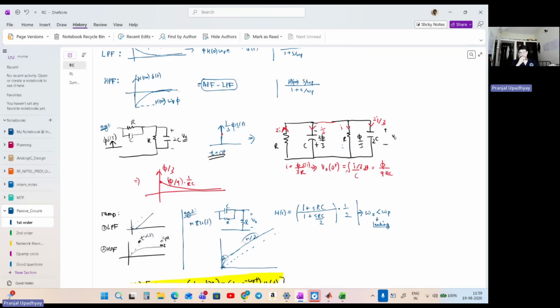Now, here, just by the look of it, typically they will mention also, but this is basically a voltage impulse. Now, let us try to discuss the behavior of the circuit. So, at infinite frequency, what will happen is that this capacitor and this capacitor will short, and basically voltage division will happen. Also, since this capacitor is larger, lesser voltage drop will happen across it, right? And since at steady state, these resistances will do the voltage division, half the voltage will try to appear across this network, right? So typically for a general input, what we can expect is that this circuit will have a lower initial value and a greater final value.